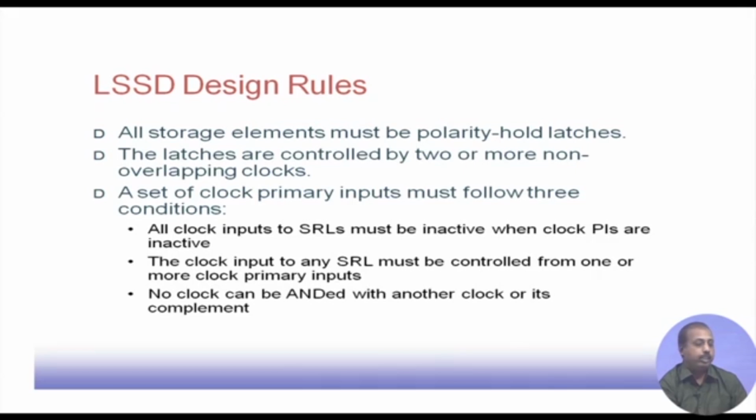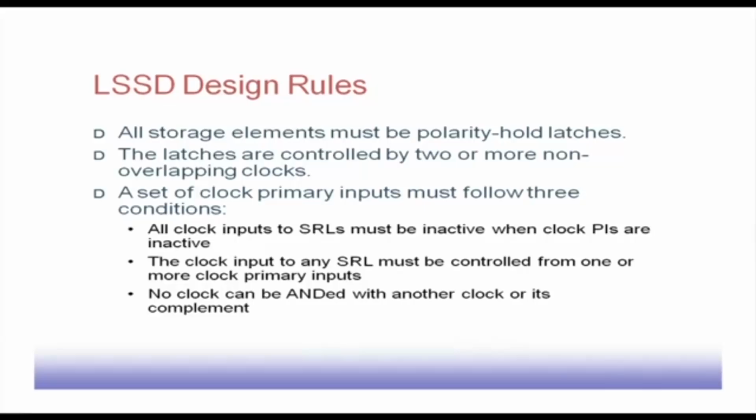If you do an ANDing, that means that line output is going to be an ANDed operation. So, that will be active only during overlapping clocks. We do not want the clocks to be overlapped, because in that case the operation becomes unpredictable.